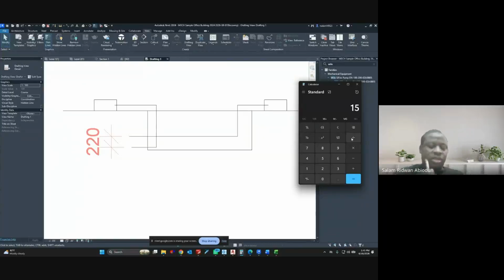So what I'm saying is, you should share 20 cubic meters and 15 cubic meters in between 35 cubic meters. So what you are going to do is say 15 divided by 35, then multiply by 1. That's 0.42. That's the first one. This will be the depth for the 15 cubic meters, which is for your domestic usage at home. If you now subtract this 0.42 from 1, the answer you get is 0.6. So it will now be 0.4 and 0.6. Do we understand?